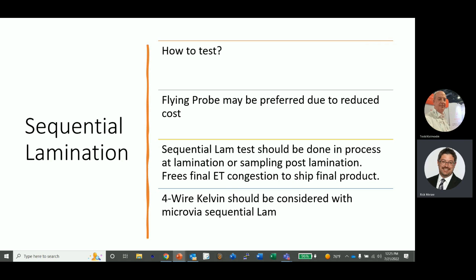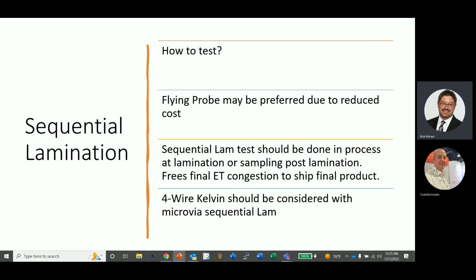So as I mentioned earlier, we can do flying probe tests, which significantly reduces the cost of it. We also have, at Gardien, we use our Accelerator 8 sometimes to scan the subassembly and then put on flying probe. It saves a little bit of time as well. And it's not really recommended to make a fixture, but I've seen some applications where they've built big fixtures and test the full panel, double-sided or single-sided at once.